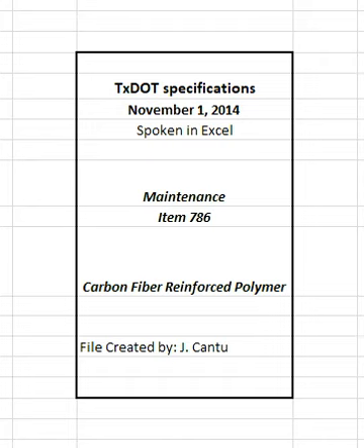Provide manufacturer's material safety data sheets, MSDS, for all materials to be used on site and certification the materials conform to local, state, and federal environmental and workers' safety laws and regulations. Provide all CFRP components, excluding fabric, in original factory sealed, unopened packaging clearly marked with the manufacturer's name, product identification, including brand, system identification number, and batch number, and expiration date or shelf life. Store and handle the products in accordance with the manufacturer's instructions. Ensure out-of-date components are not used.